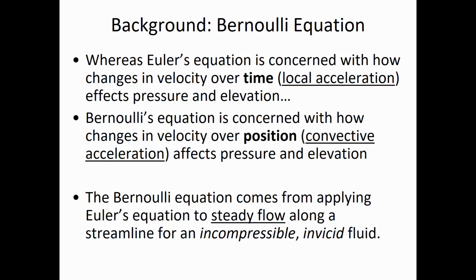Now, inviscid is a word that probably not anybody knows yet, but you're going to learn it today. Inviscid means a fluid with no viscosity. Okay, a fluid with no viscosity. I'm sure you've been poring over the tables in your appendix. Have you found any fluids that have no viscosity? No fluids have no viscosity. But between gases and liquids, which one gets closer to the description of a fluid with no or very little viscosity?